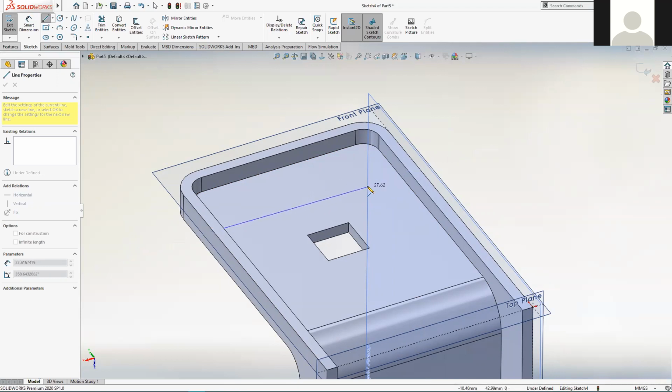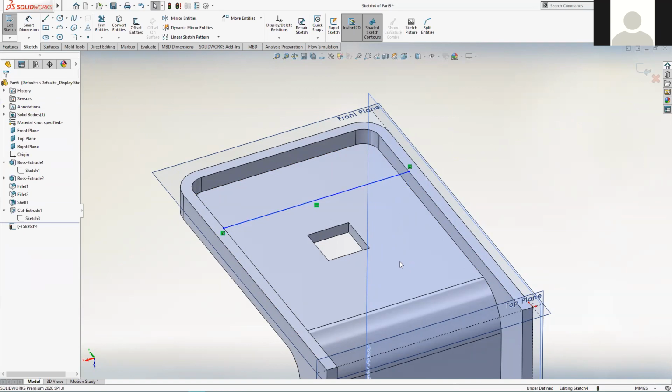So that's one of the difficulties when you're sketching from a 3D perspective. But we'll persevere. So I want to lock this line to horizontal, and I want to lock the second point, so the other end of the line that I'm about to place, to that edge. So when I get the coincident icon in yellow and the horizontal icon in yellow, then I'm going to click, and then I don't need the line tool anymore, so I can press escape.